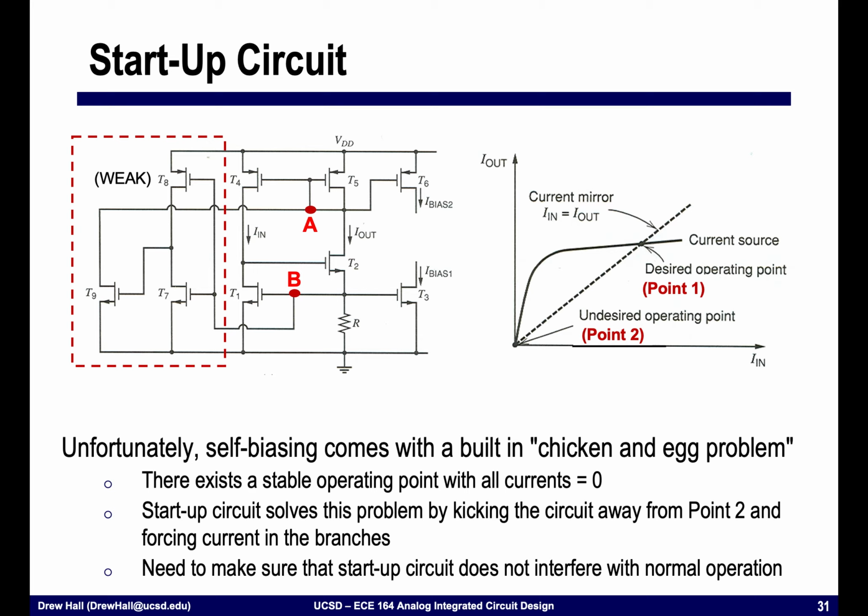And so this is what's known as a startup circuit. The startup circuit essentially looks at various different nodes within the circuit and tries to kick us out of this undesirable operating point and put us up where we're operating with current on this device where we want to operate. Okay? The way that this works is actually pretty straightforward.